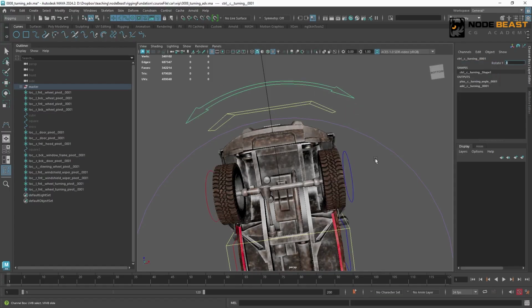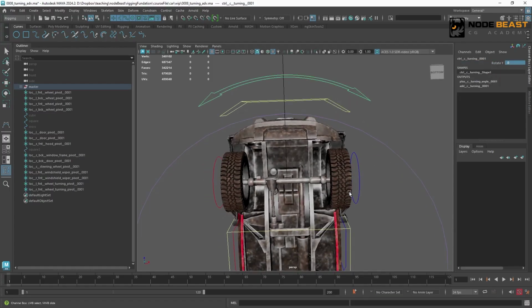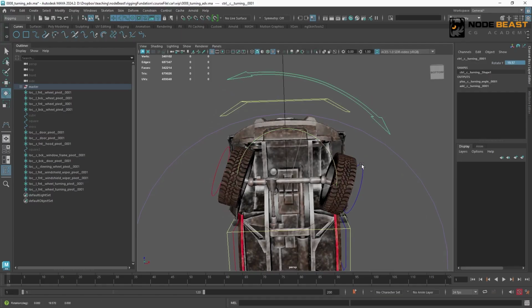Let's first briefly analyze what effect we need for wheel steering. First, as mentioned, when rotating to one side, the rotation angle of the inner wheel must be greater than the outer wheel, and these three angles are actually a comparison. This is our car body's rotation angle. The inner wheel's rotation angle should actually be slightly larger than this angle, and the outer wheel should be slightly smaller than this angle. This relationship isn't completely fixed either.